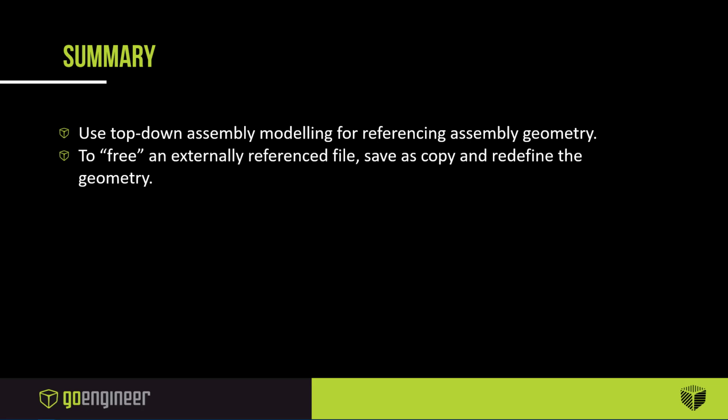Right. Next question is, once you make a virtual part, can you still modify attachments? Yes. So mates can be edited like normal within the assembly. It gets treated just the same as a normal SOLIDWORKS part does inside the context of the assembly.